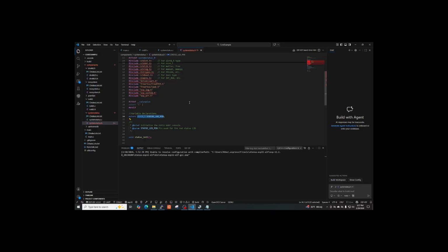That way we have a way to toggle the status LED to turn it on, to let us know that something is at fault, and then use these status bits to store what general part of the system is causing a fault, like the limit switches.